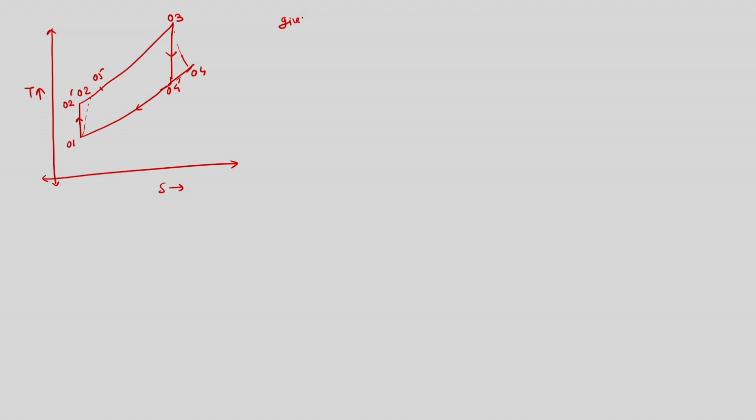So, given things in the example include compressor efficiency as 82%, turbine efficiency as 85%, so it is 0.85. We have transmission efficiency as 99%. Turbine is connected with compressor, so compressor work we will calculate, but that much work is just required for the process of compression, but we need to supply more work to get that work from the turbine. So, we practically would have compressor work more due to the transmission efficiency. So, transmission efficiency is related with net work input and we have pressure ratio as 7, combustion efficiency as